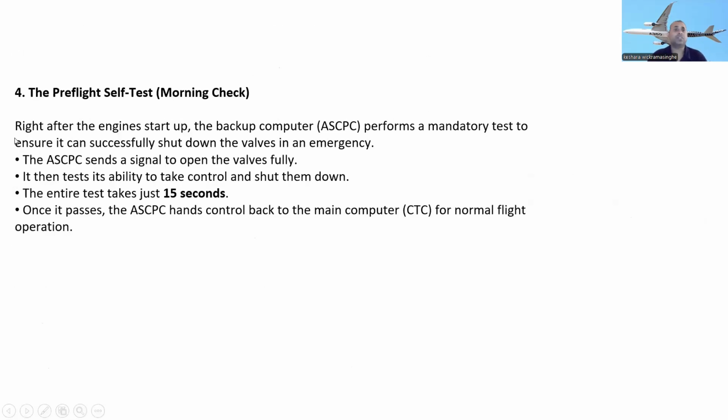Okay. All right. So, the pre-flight self-test monitoring check. Right after the engine startup, the backup computer ASCPC performs a mandatory test to ensure it can successfully shut down the valves in an emergency. Every time, the ASCPC sends a signal to open the valves fully, then tests its ability to take control and shut them down. The entire test takes about 15 seconds. Once it passes, the ASCPC hands control back to the main computer for normal flight operations.